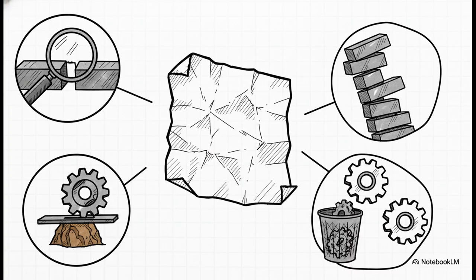First, overcomplicating your designs with super tight tolerances that aren't even functionally necessary. All that does is drive up CMM programming time and manufacturing costs. Second, misinterpreting or picking non-functional datum references. Listen to me on this one. Never pick an imaginary point in space as a datum, and don't pick a surface just because it's convenient to measure if it doesn't represent how the part actually functions in real life.